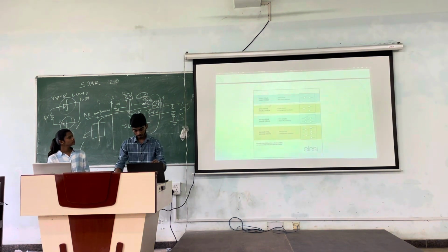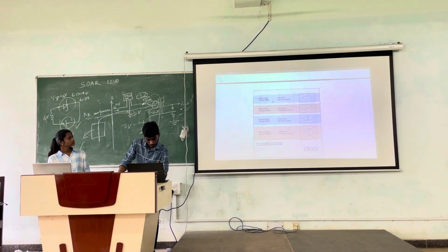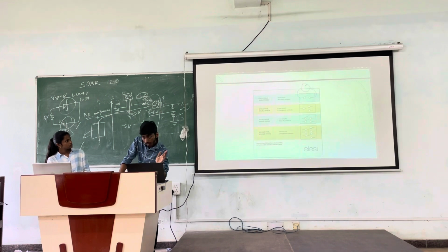Okay, so first of all, let's see single pole, single throw. Here, single pole means it will control only one circuit at a time, and single throw means only one contact point. So here we have one terminal at both the sides. We can connect one circuitry over here, and at the same time we have this one contact point here. Okay, so that's why it is called SPST, single pole, single throw. We can control one circuit and the contact point is also one.